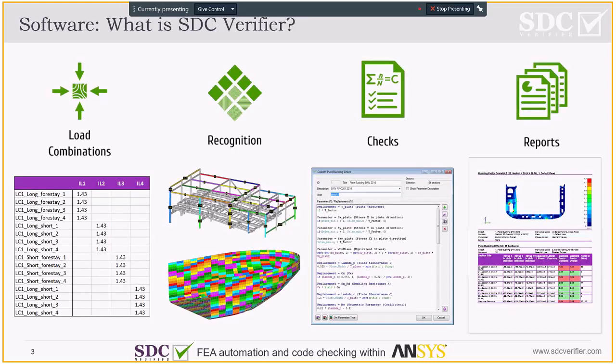So SDC Verifier is an add-on to Ansys, built on top of Ansys and built for helping you to do the code checking within your Ansys model. We have implemented the load combination tools and the recognition of structural members, because all the checks are done on the structural items such as beam members, plates, or welds, and not on the finite elements.